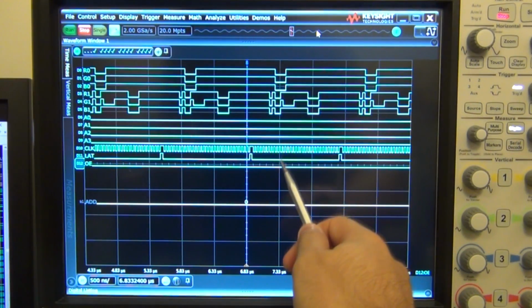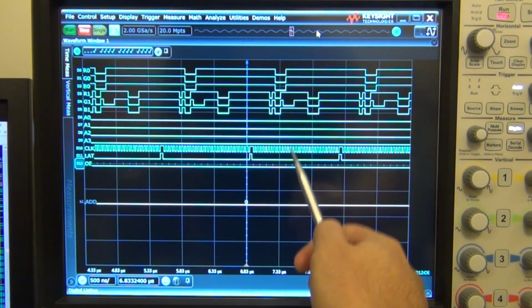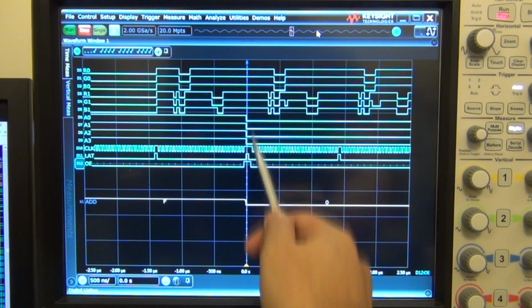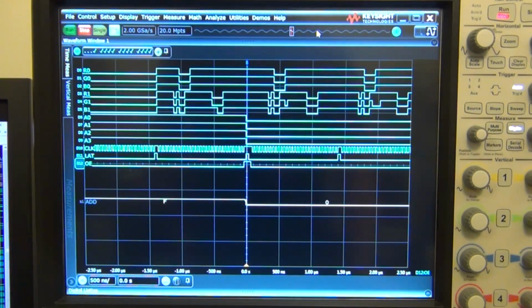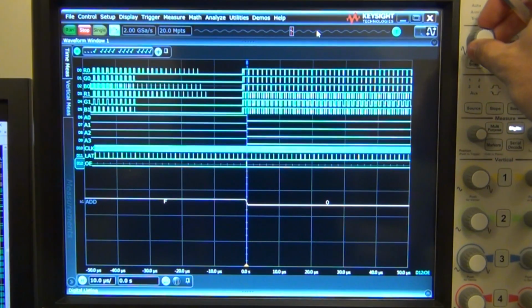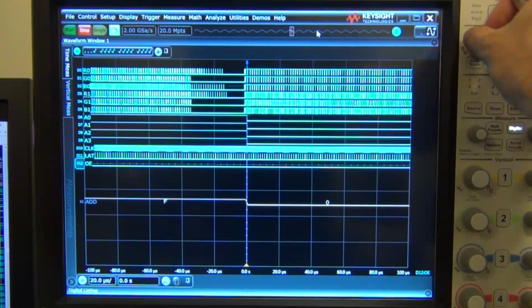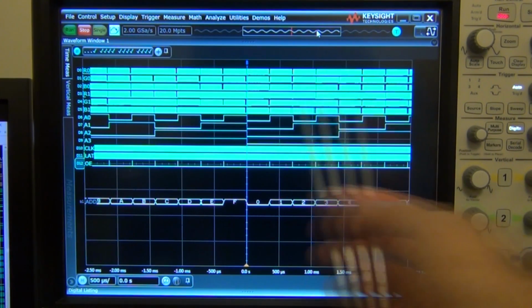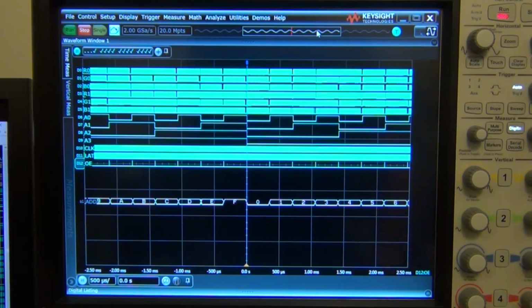And I can continue to just go on and on, and you can see all the waveform. But this behavior is exactly the same as the behavior that we saw in the simulation on the FPGA. And you can see that at the 0 line, when the address changes is when the output line actually changes. In between the different lines, you don't need to disable the output. You want to keep it enabled because you want to have the line lit up. And you can go through this in more detail, of course, but I suggest, as Timo said, download the FPGA code, run the software, familiarize yourself. Being able to do this on FPGA is a huge asset to people who like to work on this type of stuff.